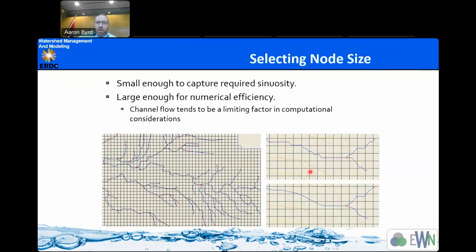Let me say something else here. Right here, what you should notice is all these little nodes in the middle, those are the points that came from the DEM. Remember, that's our little fancy grid, and we zigzagged our way up the DEM. Horizontal and vertical cell distances in our DEM are going to be our DEM spacing. So this 30-meter DEM, that's what you're going to start with. These would be like 30 meters going across right here.